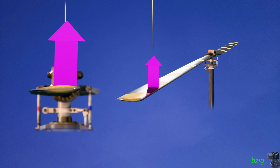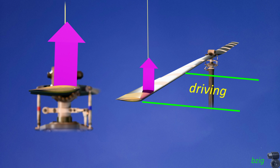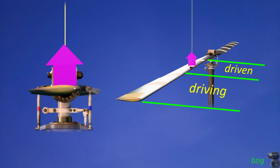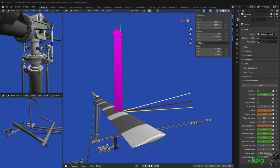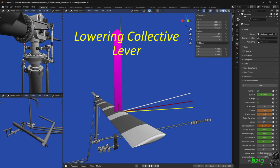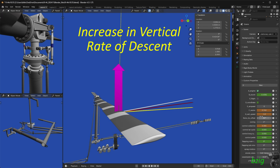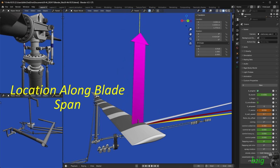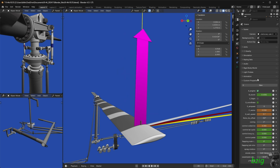Regions with the force vector tilted forward are responsible for autorotation, and we call these driving regions. Driving because the aerodynamic force is driving the rotation of the blades. The regions that create drag with the force vector tilted aft are called driven regions. The things that cause the force vector to tilt forward are lowering the collective lever, an increase in vertical descent, and location along the blade span, with the outboard sections having more forward tilt than the inboard sections.